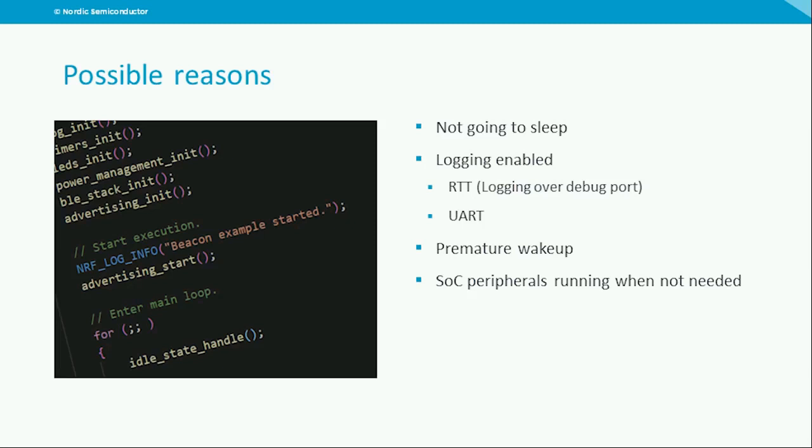If logging is needed, it is also wise to think about when we actually need logging. For instance, you can save some states in a summary when something interesting happens, and have another trigger that logs that summary to your terminal or Bluetooth peripheral when you need it.